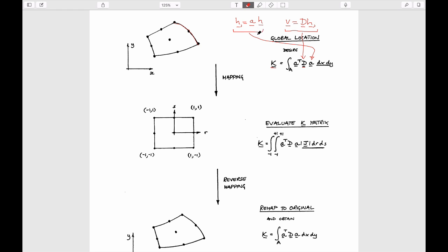That's helpful. Also, in the cases that we've looked at before, both in the prismatic element where you have a nodal value at node 1 and node 2, the variation in the heads between those has been linear, and therefore the derivative of those is constant. And so both for the triangular element and for the linear brick elements that we've dealt with, the value of A has been constant as well.